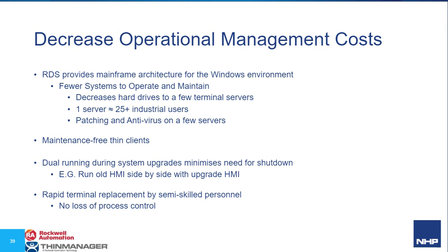Remember, when a server goes offline, ThinManager still delivers the content from a backup source. I patch that server, test it, and boot it as many times as I like, then click a box, put it back in service, and rinse and repeat on the other machines. Thin clients themselves are completely maintenance free. I can dual run systems if I like, so I can have multiple HMIs on the same screen if I'm doing a failover or a system replacement. And then even if a thin client does fail, it's very easy to replace.